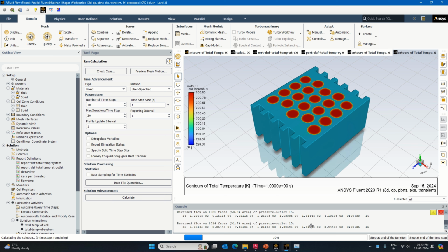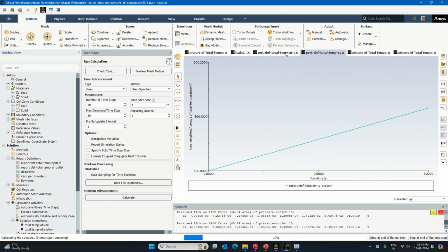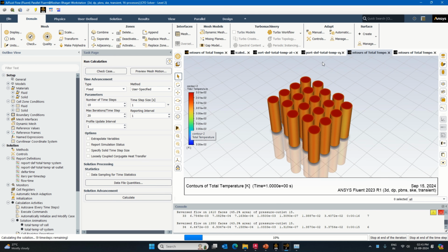So we can see the changes in the color contours which are there. Along with that, we are able to see the variations in the temperature also, how they are taking place. So depending on how the fluid is flowing from inlet to outlet, we might see some variation in the form of delta temperature at outlets also. So this is the temperature of cell. We might need to change this scale to exponential one.